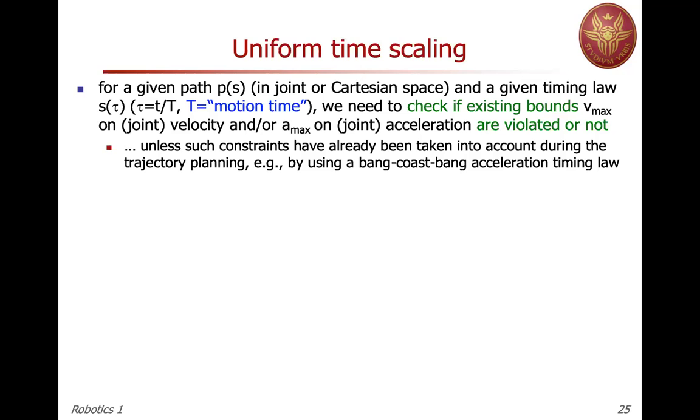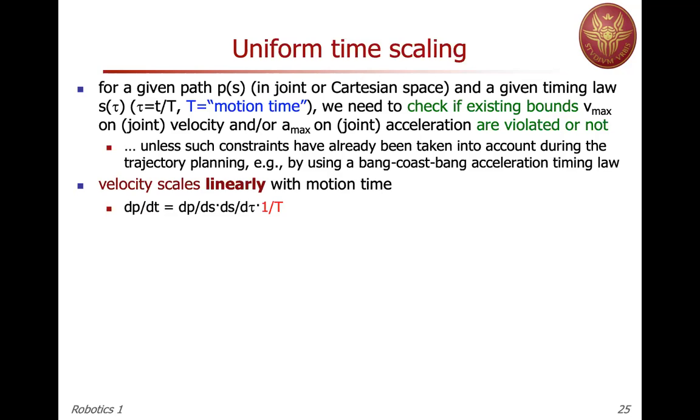And now we discovered that either the trajectory is unfeasible, or it's very slow, too slow for the capability of the robot. So we could decide to scale time uniformly. Sorry, exactly the opposite: if it was too fast, so we would like to move from 2.5 seconds to 4 seconds, 5 seconds, 10 seconds, and so on.